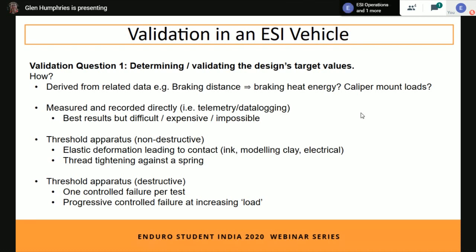So for example, going back to drive shaft torque, if once again you have a two-piece drive shaft, say an outer sleeve which goes over an inner core, so an outer sleeve from one end of the drive shaft and an inner core from the other end. Where they overlap, you have a pin going perpendicular through the two of them, and obviously that pin is loaded in shear as the drive shaft conducts torque. And for different size pins, it will eventually shear off at a certain torque level.